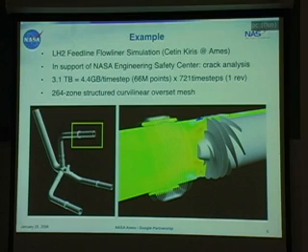So just to motivate things, here's an example. Here's a typical data set we might see. This is part of the fuel injection system of the shuttle. On the left, this big pipe coming down is the pipe that delivers liquid hydrogen from the external tank. This is the giant tank that the shuttle is bolted onto when it lifts off. It's about 16 inches across, just to give you some scale. And that brings the liquid hydrogen down. It trifurcates, and each one of those three subpipes feeds one of the engines. And at the end of each one, and we have one of them surrounded in a box, there's a relatively low-speed impeller. There's a close-up on the right, and that moves the fuel into a high-speed turbine that actually blows it into the engine.